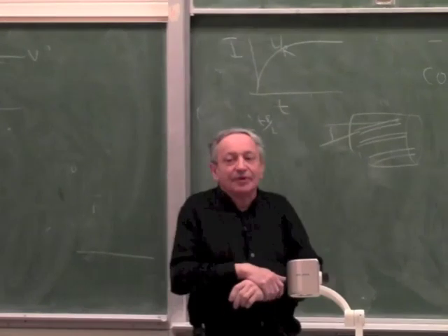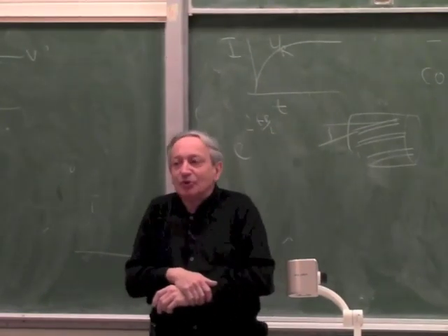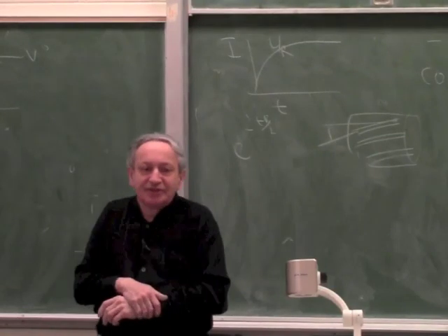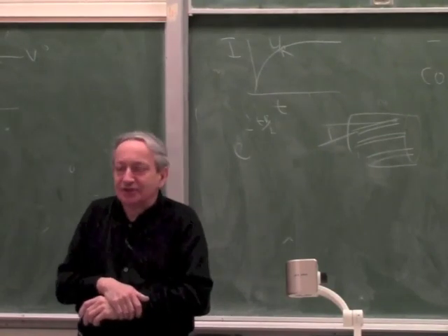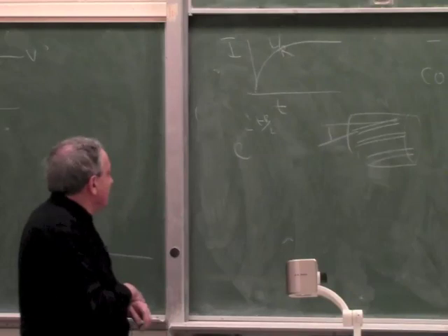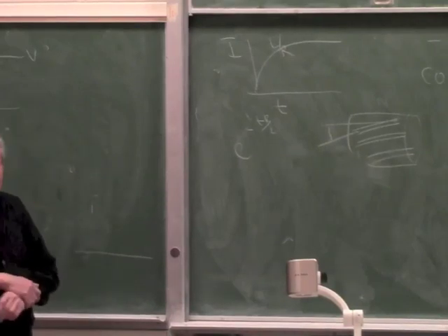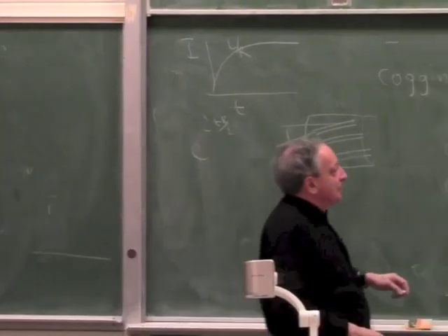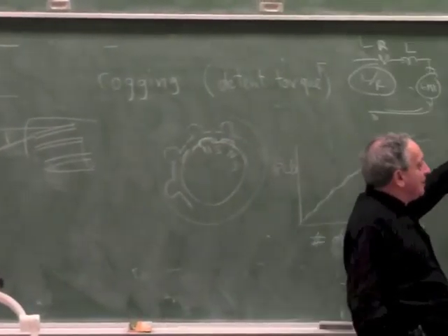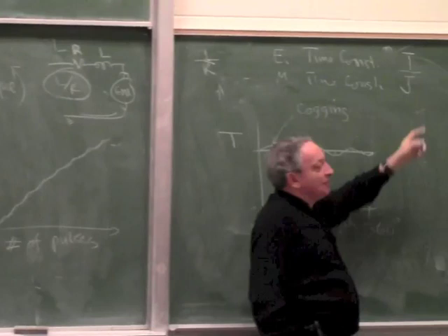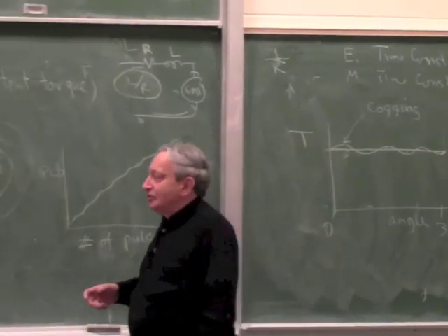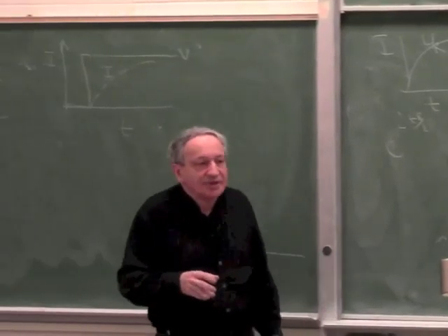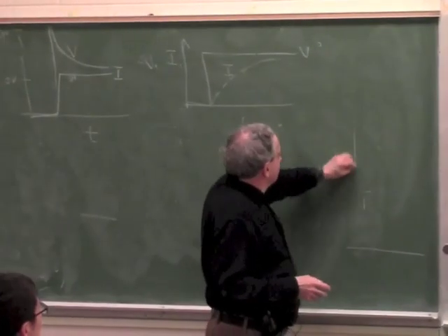Now if motors are designed for very high performance servos, they also have a different construction, because if you look at a typical PMDC motor, you want to maximize the torque to inertia ratio, so you're trying to minimize inertia. So if you look at the armature of the motors I showed you, they had a piece of steel.